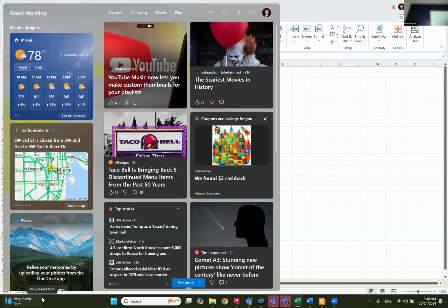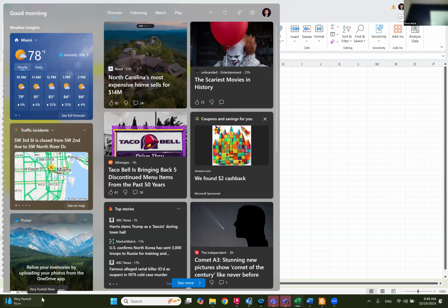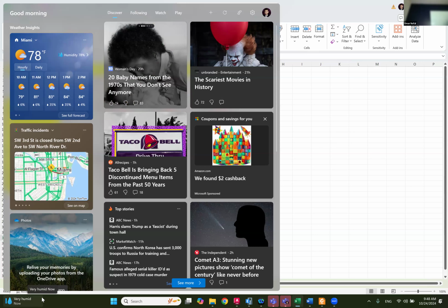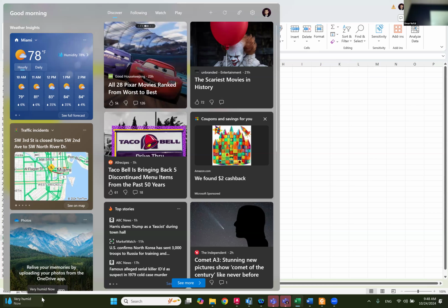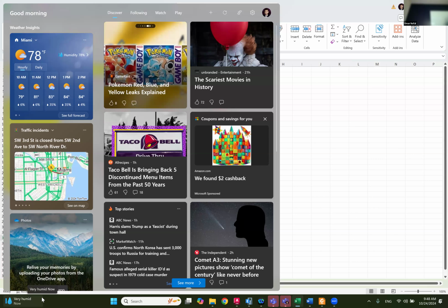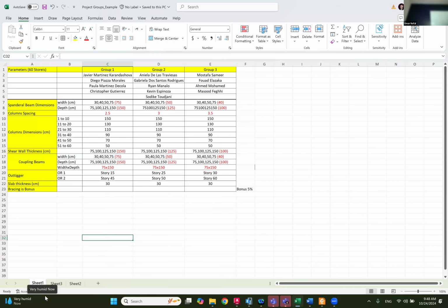So let's say my building is like this, and these are my stories in ETABS. What I'm going to do, I'm going to connect here to here, and then here to here. I go story by story. And once I hit here, I go the other way. And same thing from the other side. I keep doing the same until I get to the other story. It doesn't mean that it has to be like here. It's okay if it's hitting a specific story, something like this, that's fine.